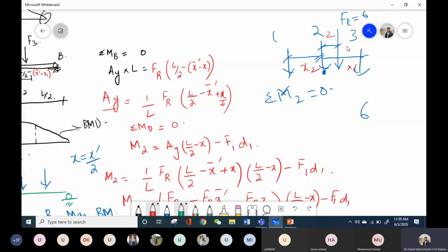So you will take the bending moment, so that will be 1 multiplied by x2, plus 3 multiplied by x1, and Fr multiplied by z. You know this x1 and x2, and then you will get the distance of this resultant. And then you will take the half of this distance and place your point load at that distance from the center line to get the maximum value. Did you get my point? Yes, sir.